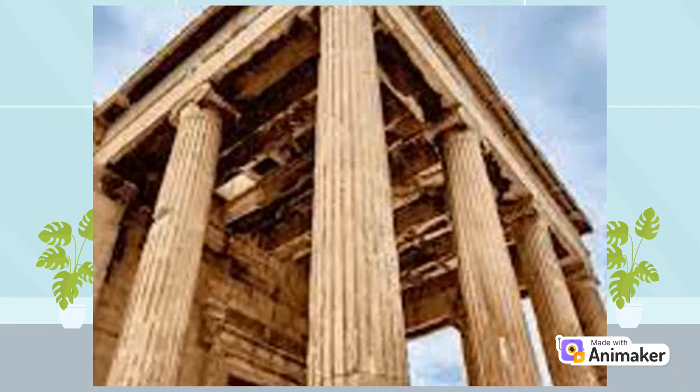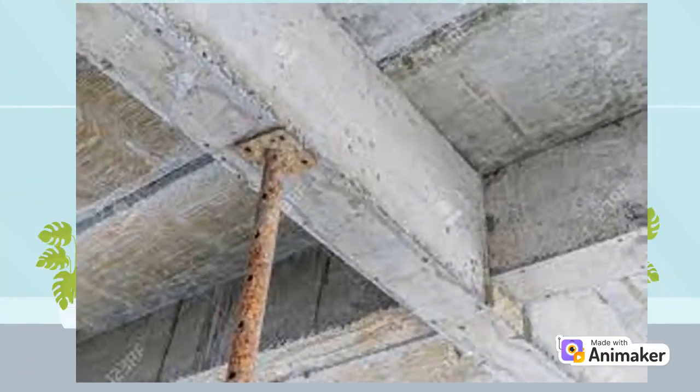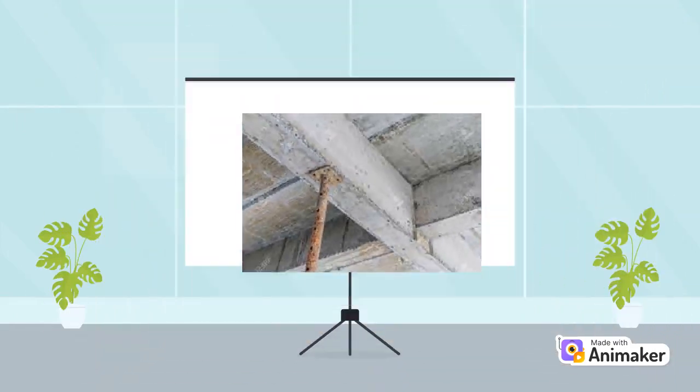Supports can be either at the end or at any intermediate point along a structural member or a constituent part of a building, and they are referred to as connections, joints or restraints. Building support structures, no matter what materials are used, have to give accurate and safe results. A structure depends less on the weight and stiffness of a material and more on its geometry for stability. Whatever the condition is, a specific rigidity is necessary for connection designs. The support connection type has effects on the load-bearing capacity of each element which makes up a structural system.